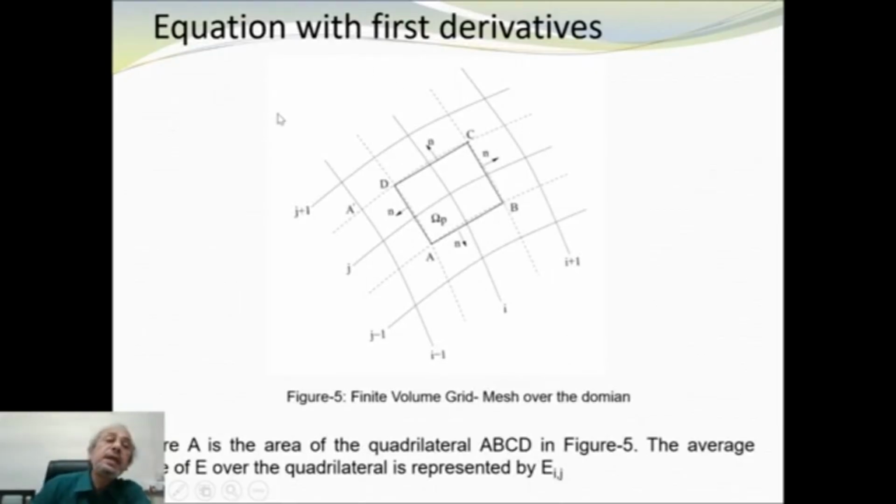As I said, if we generate a body conforming grid which will be constant eta zeta lines, then we can identify a specific control volume, say as we have defined A, B, C, D. Now entire domain we can identify such control volumes which will have additive property, and that is how the whole domain will be covered. If we write down governing equation for one control volume that is valid for all the control volumes, and finally we will be able to get the matrix equation.